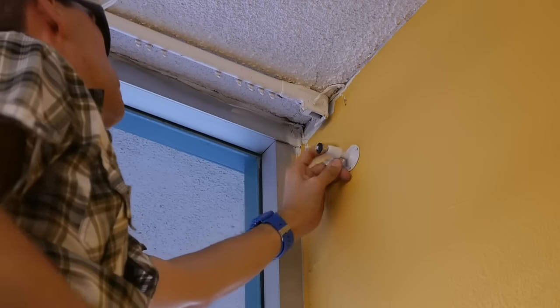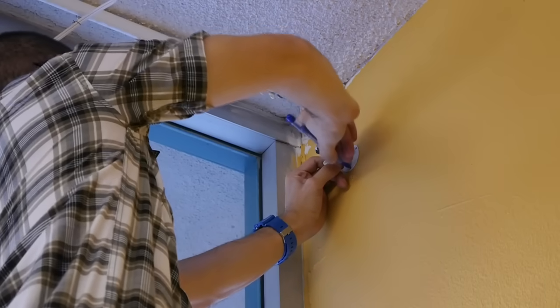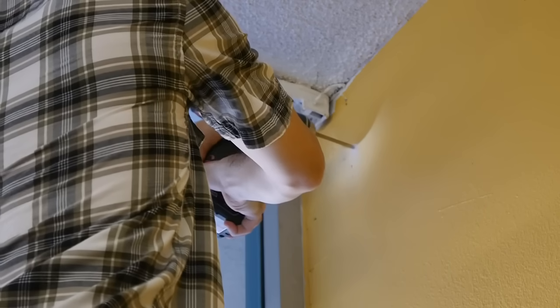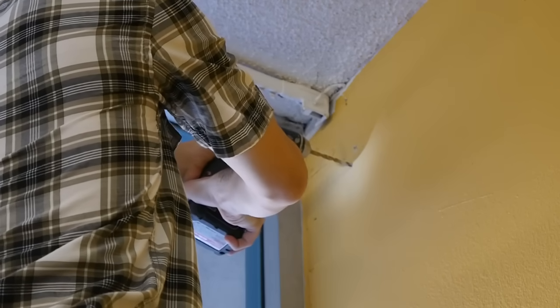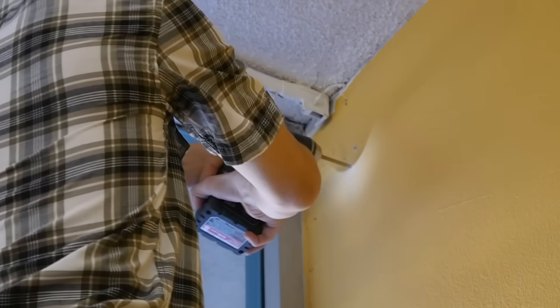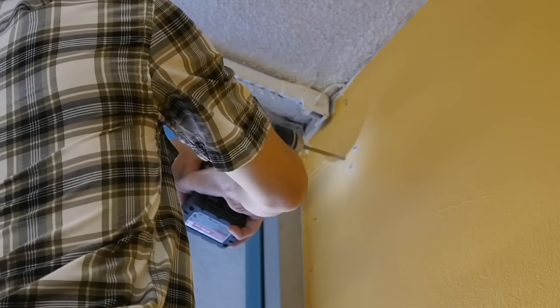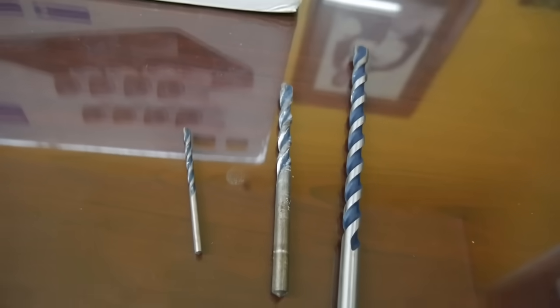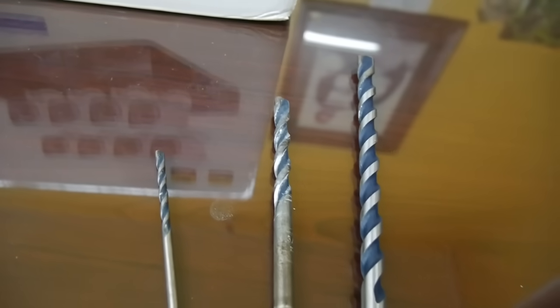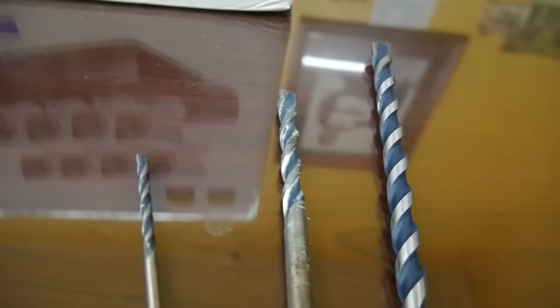After you figure that out, it's finally time to mount the cameras. Place the base of the camera on the wall, and with a marker, mark each hole in the base. Then drill each mark using a drill bit that's the same thickness as the anchor you'll be using. This is so that the anchor is nice and snug. You can use any drill bit for making holes in drywall, but if you're planning on drilling into plaster, stucco, brick, or concrete, you'll need to use a bit for drilling masonry.